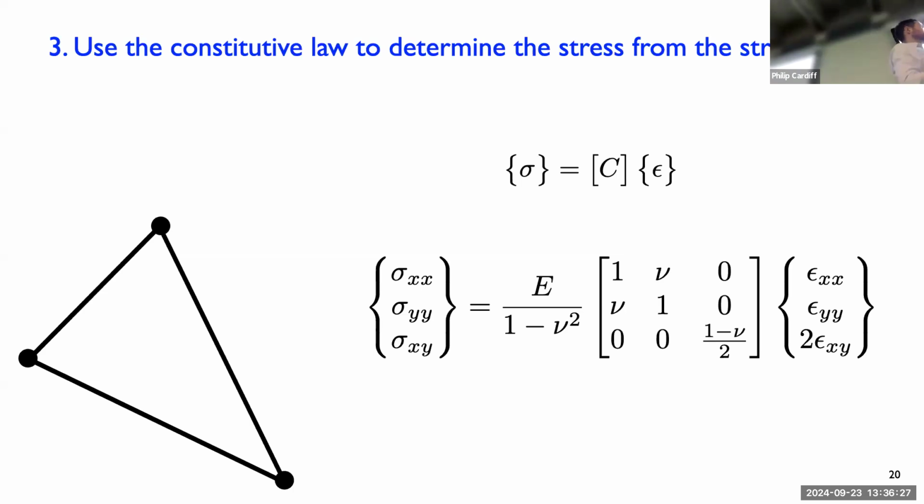But when Poisson's ratio is not 0, for example for steels or other engineering alloys, it might be, let's say, around 0.3. In that case, the stress is equal to E divided by 1 minus 0.3 squared. That's a number less than 1, so that makes it apparently higher. Because of Poisson's ratio, it seems kind of stiffer in the direction you're pulling. And then it'll be 1 by your strain in the XX direction.